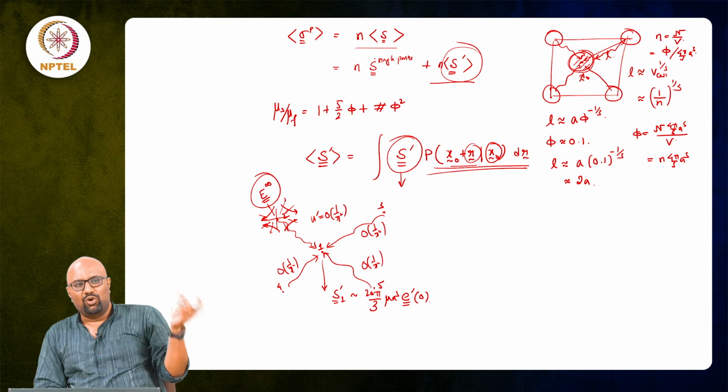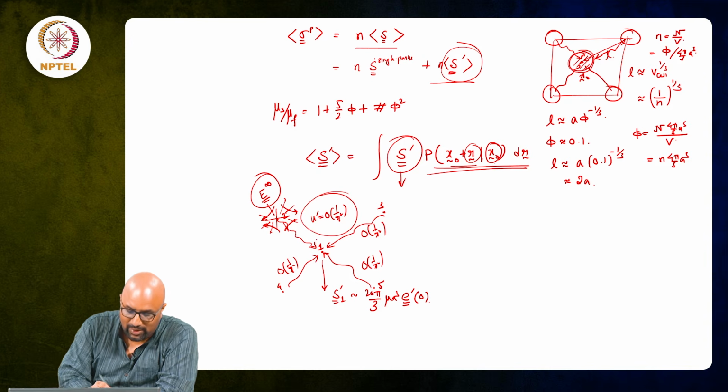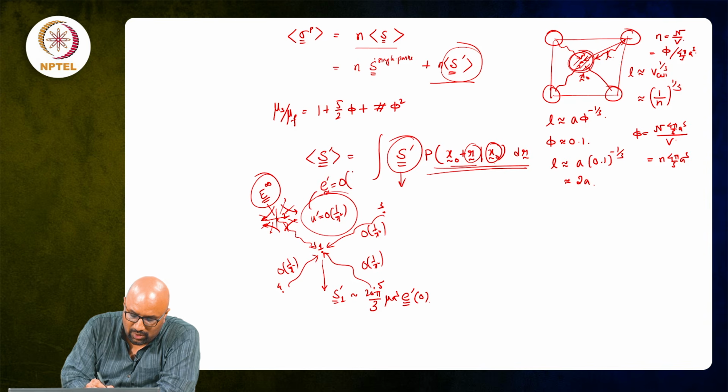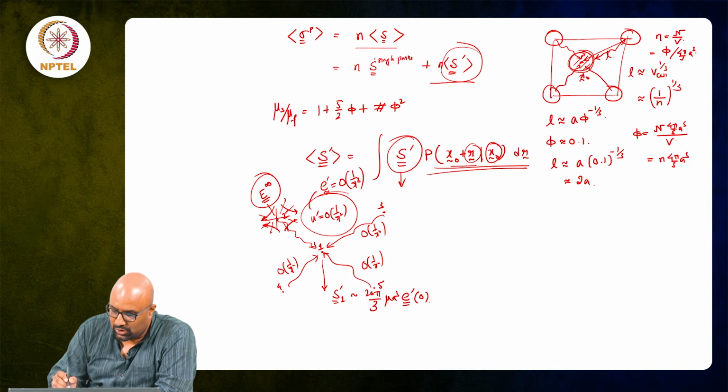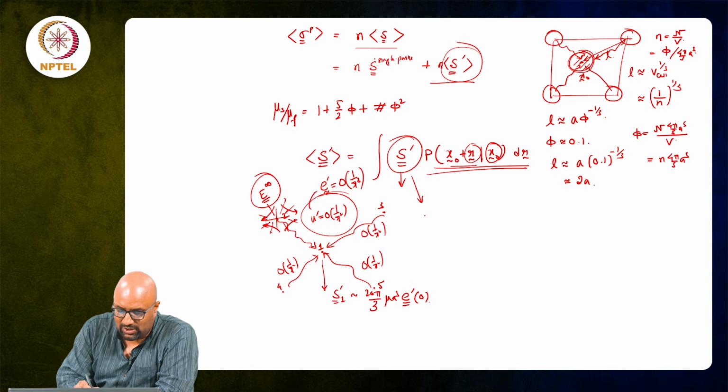So, each of those individual disturbance flow fields are going to go as order 1 over r square. So, their respective strain component is going to go as order 1 over r cube. If the velocity goes as 1 over r square, the velocity gradient and the strain component should go as order 1 over r cube. So, in this, the strain part, the disturbance stresslet part should have a term that is 20 pi by 3 mu a cube and an order 1 over r cube term.